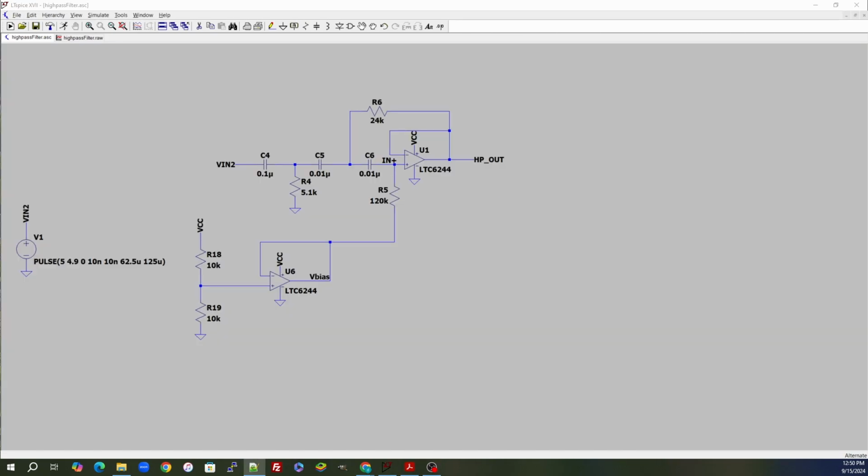So what do we want to do? Well, based on the fact that we have a 100 millivolt pulse coming into the input, and it's giving us the 100 millivolt output on the high pass filter centered around 1.65 volts, if we have a gain of 2, we want to be able to see that 200 millivolt swing on the output somewhere that we can feed into our microcontroller. But we've already seen that we can't have it biased at the 1.65 volts, otherwise we'll saturate our gain amplifier, right?